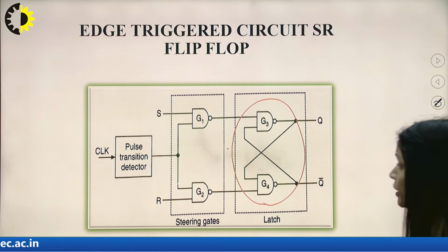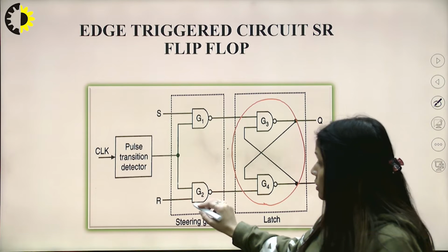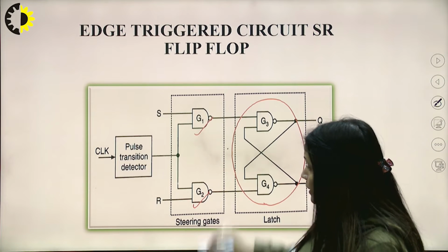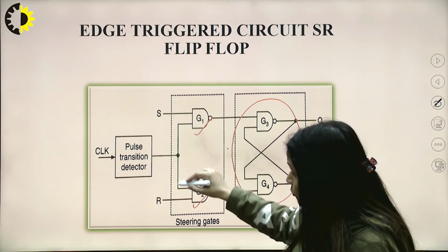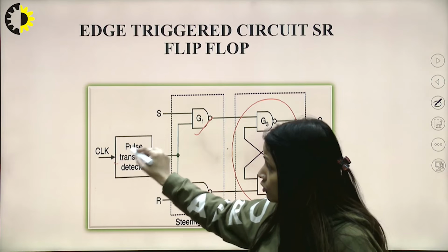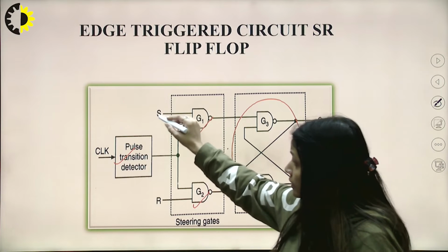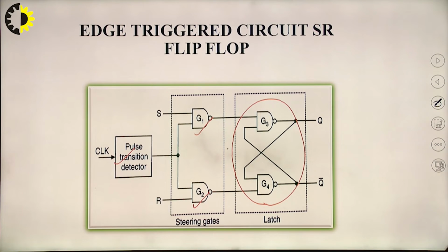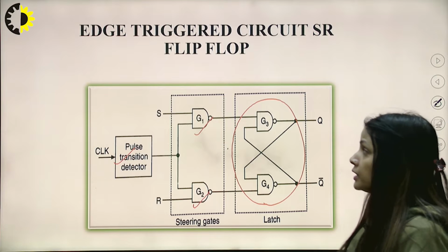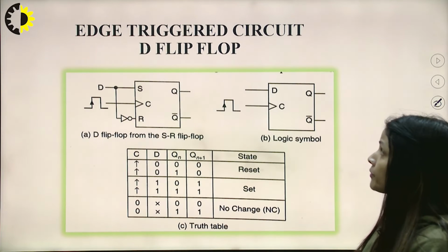We have added 2 more NAND gates to our SR latch, and both NAND gates are connected to the clock in this way. Here S and R are the inputs for this particular flip-flop. Again the table and the working are the same for the flip-flop.